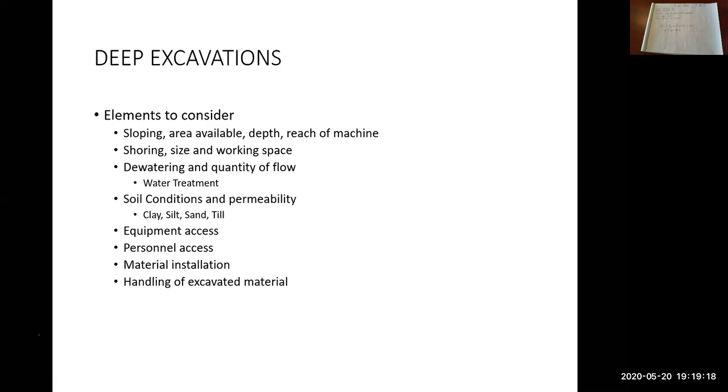You would set up a scaffolding type stair tower. Those can be rented, or fabricated on site. So personnel and equipment. So the workers carrying their hand tools, carrying, you know, bits of lumber, plywood, etc., all that type of stuff. How do you get it down to the bottom?